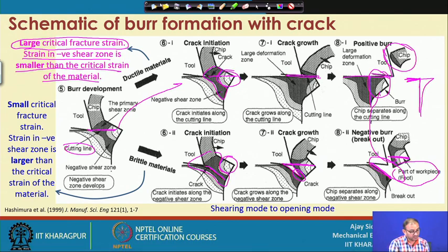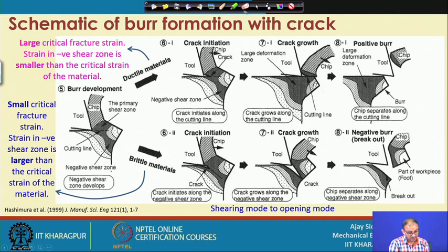Now how are these things different in both the cases? Consider two situations here. This is our objective, that this should be the workpiece, but here we got one additional part, correct. If you apply a deburring operation here, there is still a chance that you can get this workpiece out of it, because you remove this part with some type of lapping operation or cutting operation.